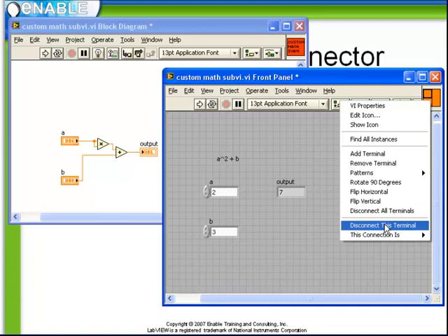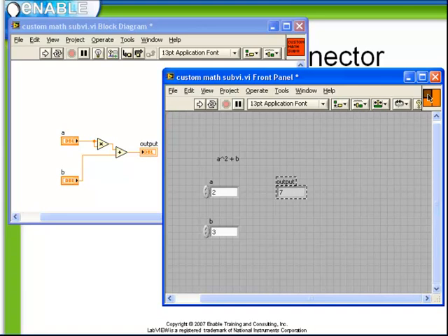One additional important point about the connector terminals is that when we click on one terminal, notice how the linked control is automatically highlighted. It's a very useful way to double check that everything has been connected properly. Similarly, when we select a control with the wiring tool, notice that the relevant terminal is highlighted on the connector.